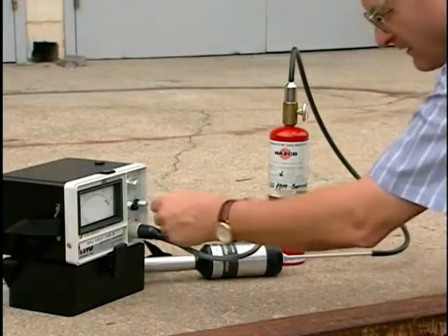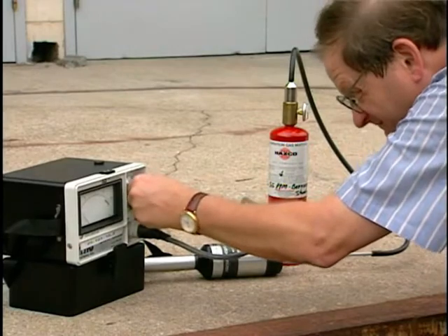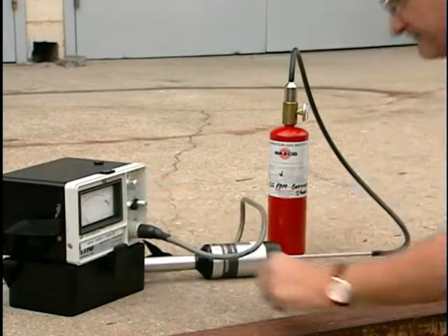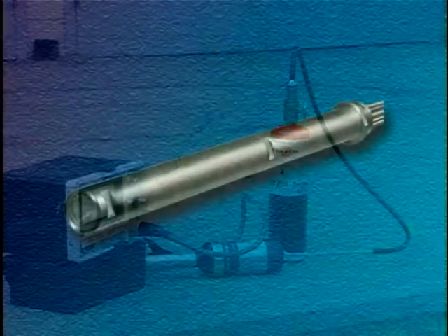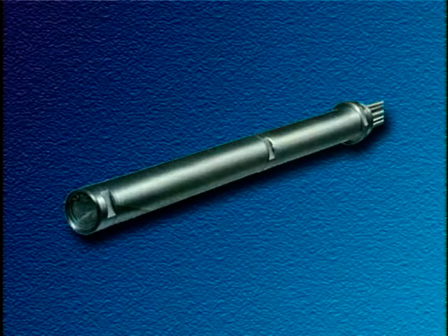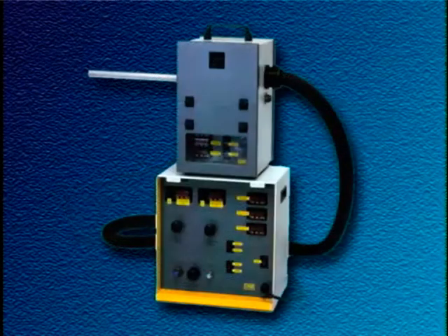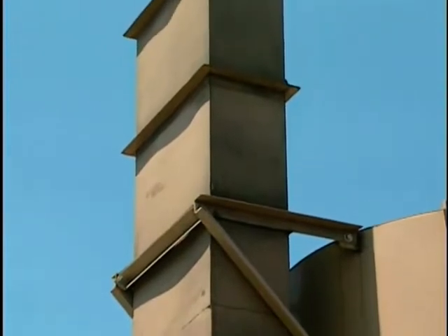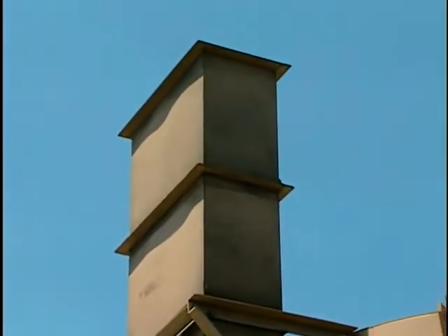If there is no permanently installed analyzer, the concentration measurements will have to be performed with a portable analyzer. However, a dilution probe may be necessary to avoid temperature damage to the instrument. Due to the limited pump capacity of these analyzers, measurements must be made in the portion of the outlet ductwork that is under positive pressure.